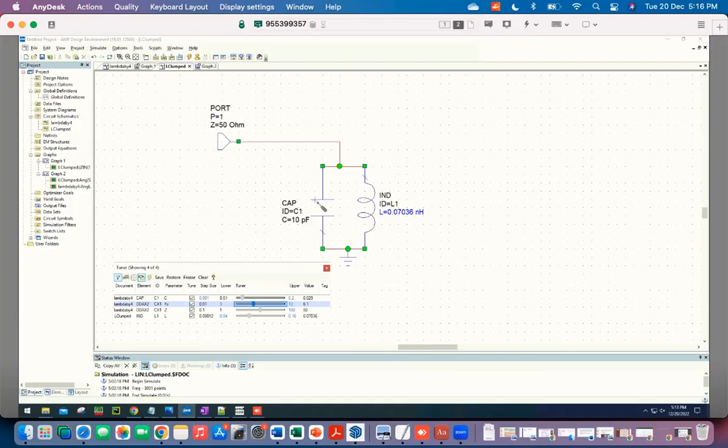So even for lumped element circuits, if there is some particular need and you want high Q, you can do the same trick. You just put a series capacitor here, and it works in exactly the same way. Right? So this is one resonator, which is some lambda by 4 section. You can think of that, and then you put a capacitor here. Right? Here, of course, there is no picture of waves multiple bouncing, but the two are completely equivalent pictures.